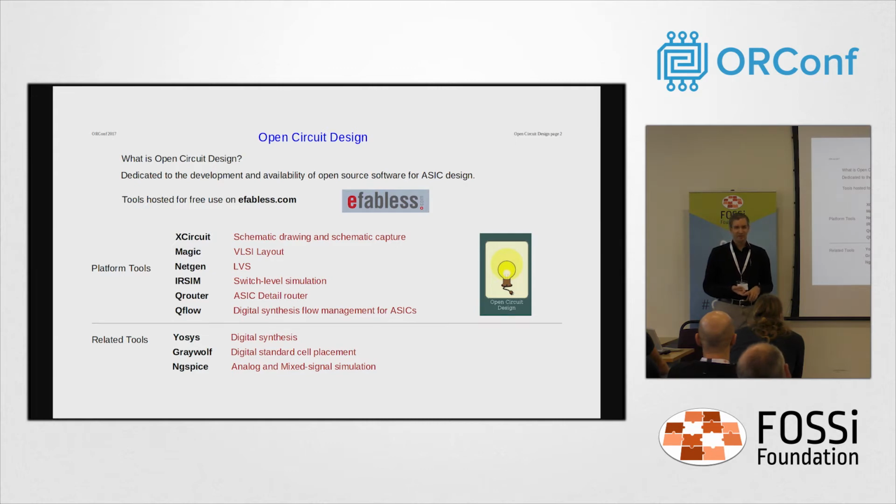They will need some kind of digital infrastructure. If nothing else, you want an SPI. Almost all analog chips right now will have some kind of SPI interface so that you can make the analog as freaking complicated as you want to. You just need a big register set where you set all the configuration bits, and you do all that when you power up.